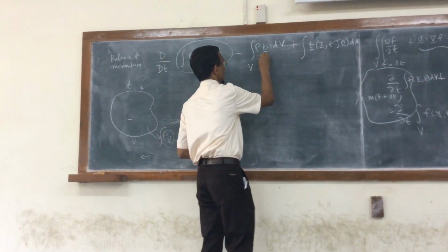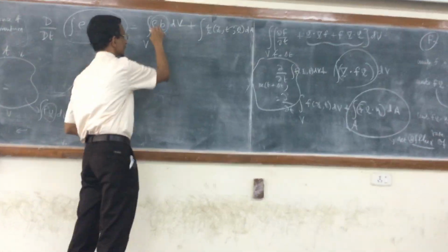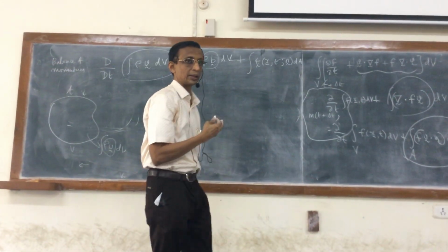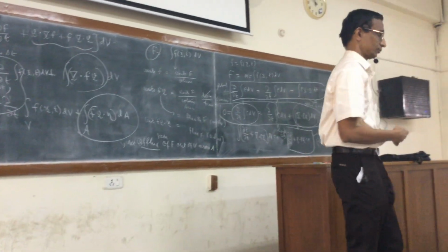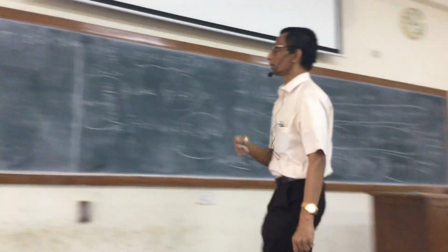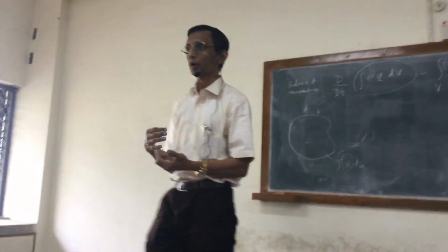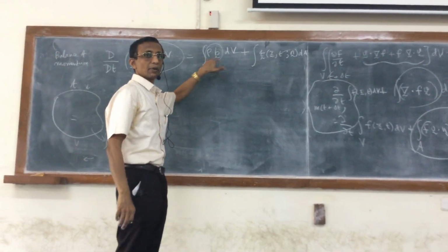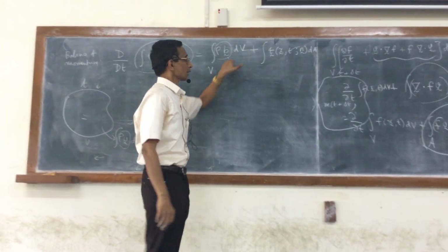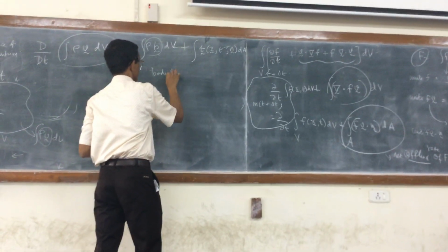That is equal to, this is the body force density per unit volume. Conventionally it is rho times P, where P represents the body force per unit mass. That's the convention. So we pointed out earlier also that to calculate the body force on this body of fluid, we need to know the body force density at each and every point within the volume, and then the so-called contact force or the surface force.